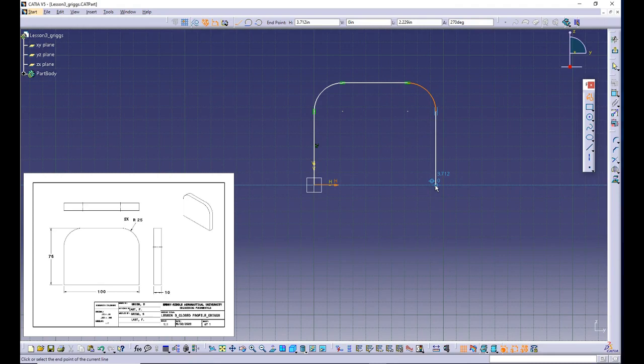And you can see that that horizontal line turns blue to help guide you to that connection. It kind of helps you create symmetry whenever it's possible. Click that point, go back to the origin, and finally click that point there to end off my closed loop. So now when I deselect, I'm going to have a couple of lines and a couple of constraints that are automatically generated for me. Now in order to make this fully defined, I'm going to need to add some constraints.